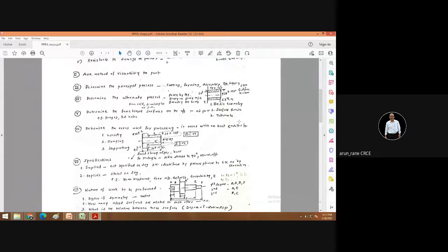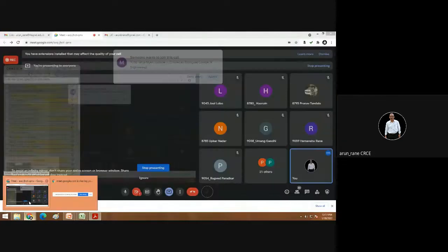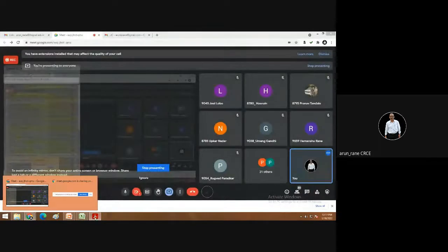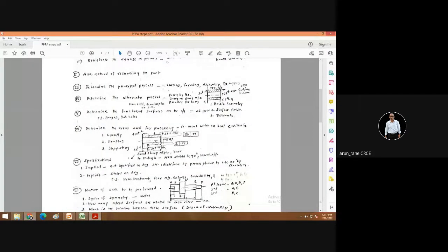So the moment we say 3 triangles or read 4 triangles, immediately it strikes us, yes, this is a ground finish or this is a lapped finish. That means this surface is important. Something is going to slide on this, or it is a working surface. Like say cylinder and piston arrangement. Those are all lapped. The engine cylinder bore is lapped always. Why? Because the piston is sliding inside there. So based on the surface finish, you identify this is a functionally important surface.